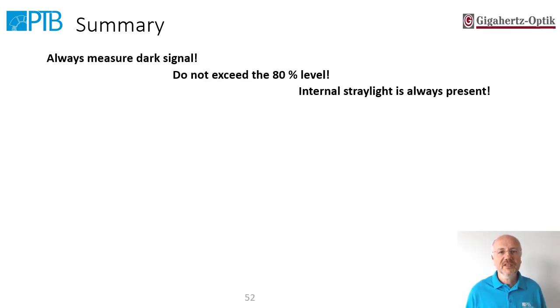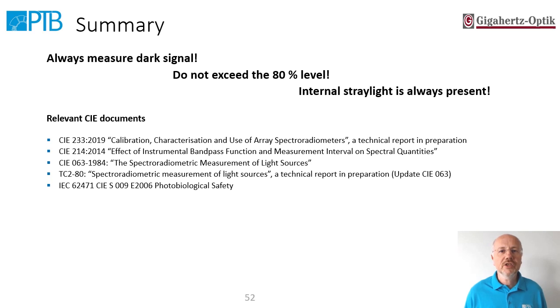Please remember these 3 rules of thumb. Always measure the dark signal, never exceed the 80% level, and internal stray light is always present. If you need further information, you can find them in the document listed here.